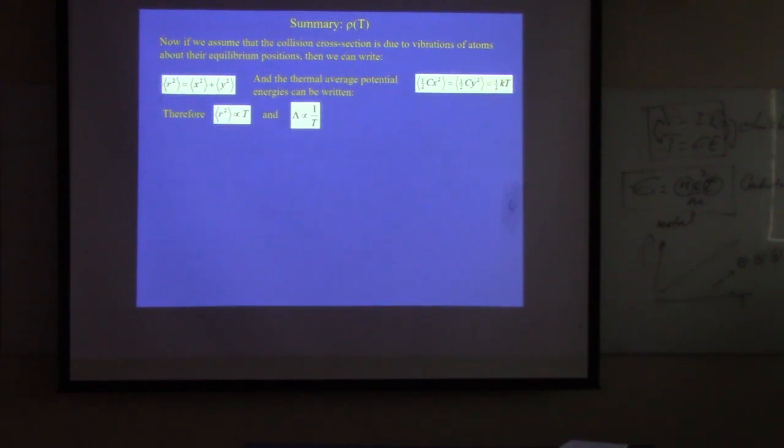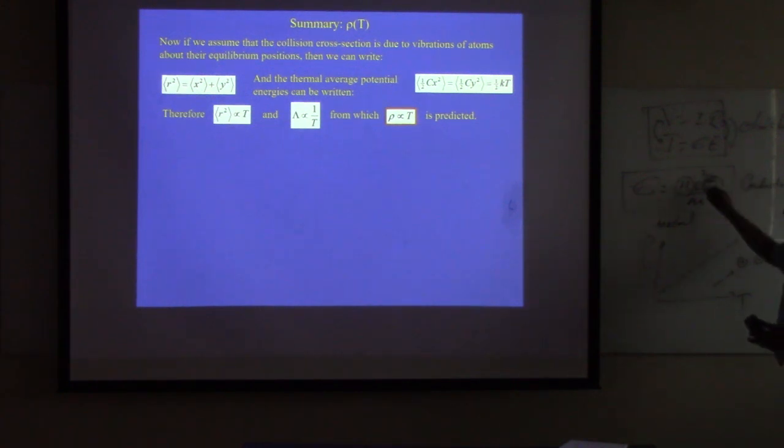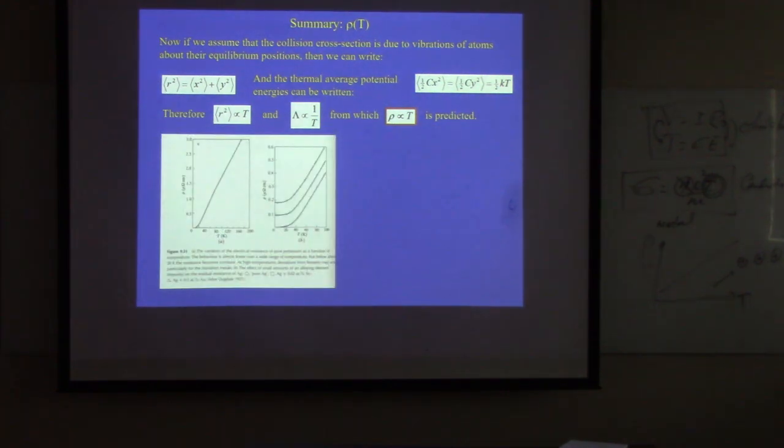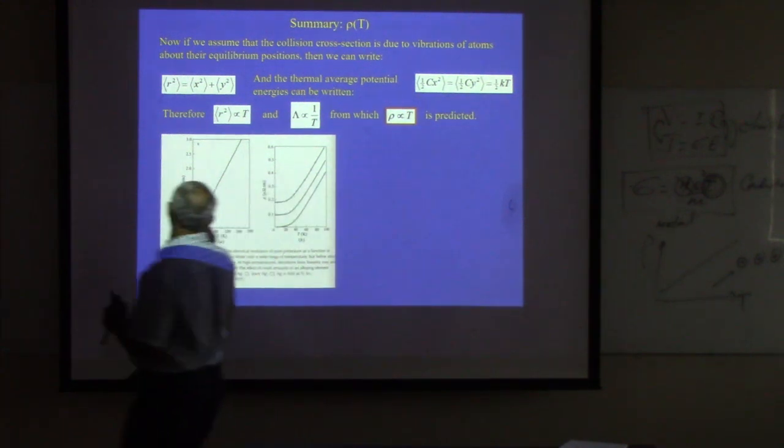Velocity, yeah, because mean free path is smaller, right? That's why V becomes smaller. So that means rho is proportional to T. Is that it? So please remember, metal conductivity is totally determined by tau, not by N, because N is already so large. So the tau depends on the collisions, right? So if you have high temperature, you get more collisions.